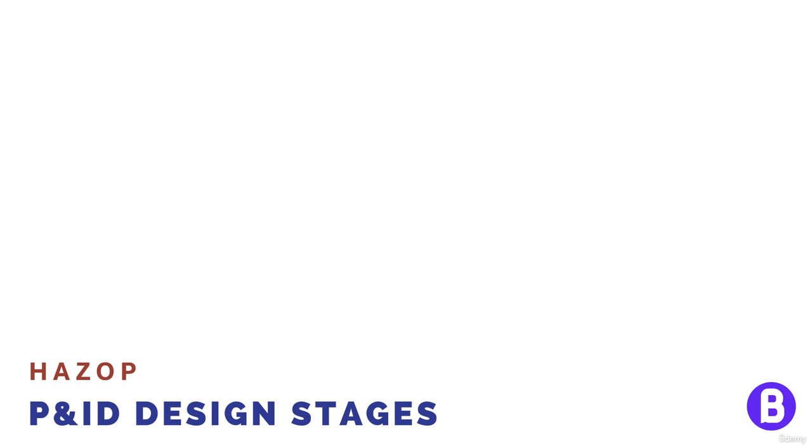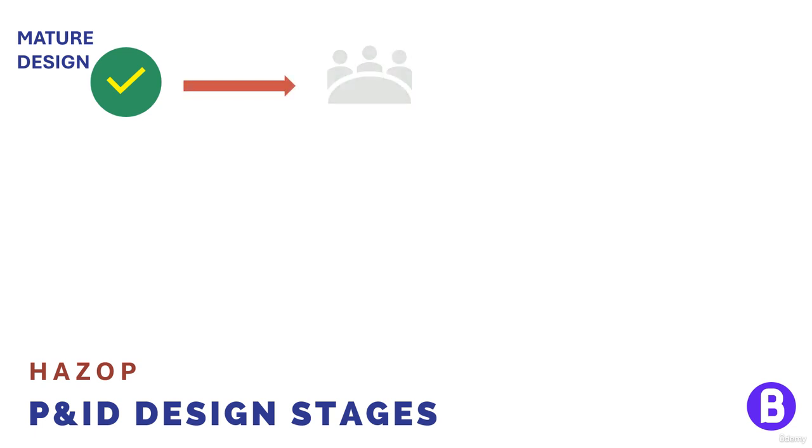With the issuance of the P&ID for design, we are supposed to have raised the main outstanding issues. We have received feedback from the vendor proposals, and we have shown the piping and instrumentation details with a very high level of accuracy. Now, the design is considered a mature design, so it's ready to be assessed from a safety and operability point of view.